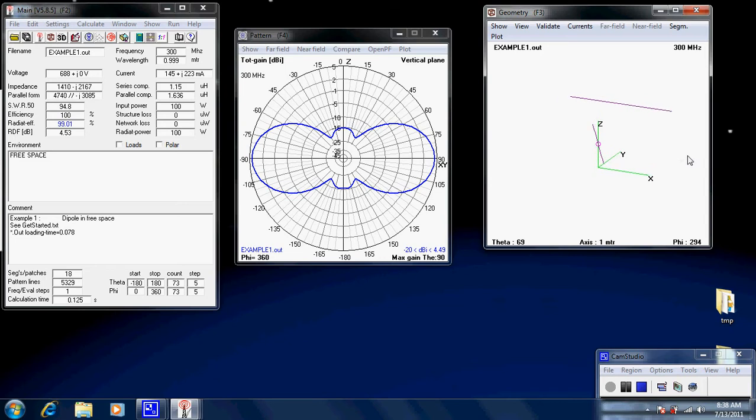The way that you actually enter information into the editors is in three dimensions. You have to define an antenna as a point in three-dimensional space. We use the three-dimensional coordinate system, x in one direction, y in the other, and z as the height. So that's all there really is to it. Each wire is defined as a beginning and an end. So each end of the wire will have an x, y, and z coordinate, and the other end another x, y, and z coordinate. And that's really all there is to it.